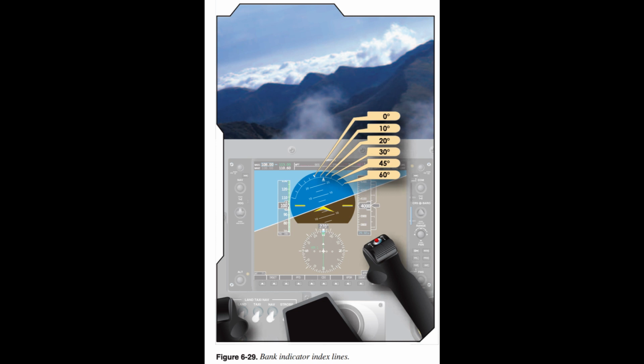Control and power instruments are the foundation for precise attitude instrument flying. The keys to attitude instrument flying are establishing the desired aircraft attitude on the attitude indicator and selecting the desired engine output on the power instruments. Cross-checking is the vital ingredient in maintaining precise attitude instrument flight.